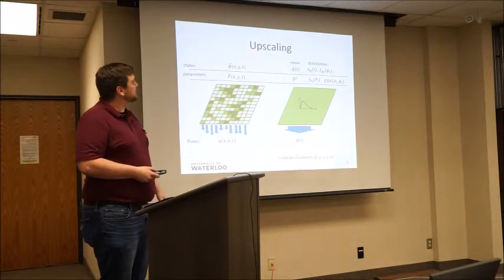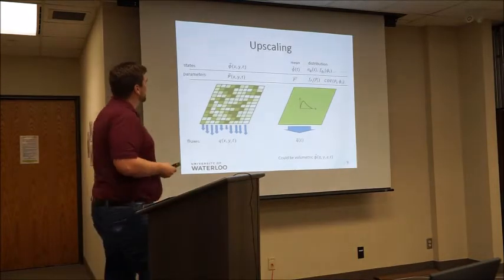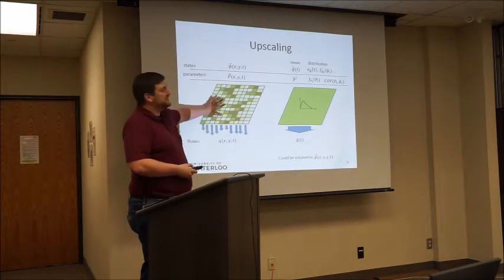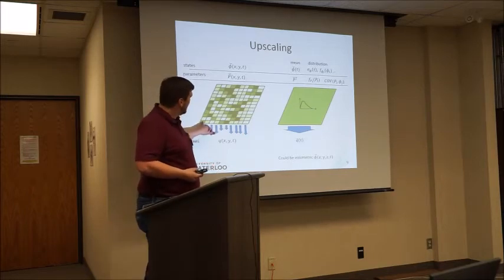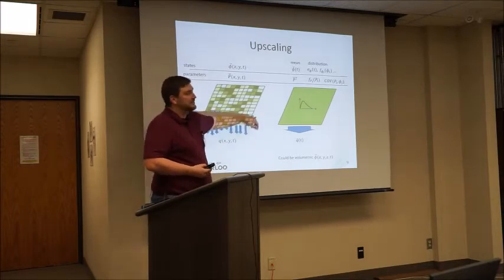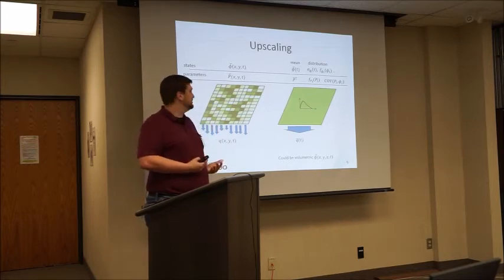So basic process of upscaling, just to go through a few details here. I just want everyone to, again, be on the same page. Here is a heterogeneous domain. We're just going to look at a simple infiltration process. So this is a system where we have maybe different porosity, different hydraulic conductivity of all these different panels, and this is what introduces the heterogeneity.